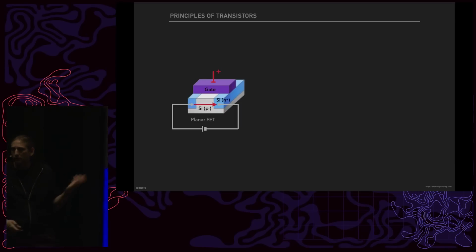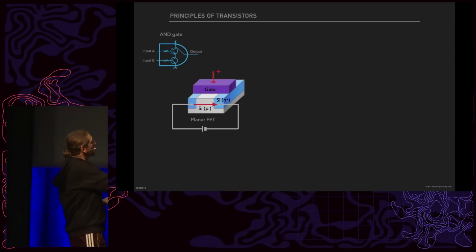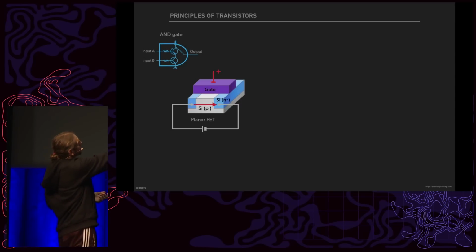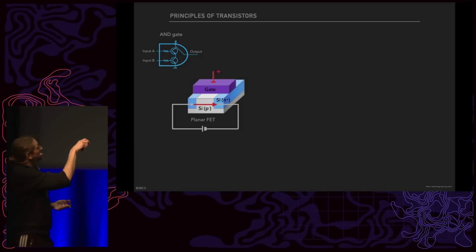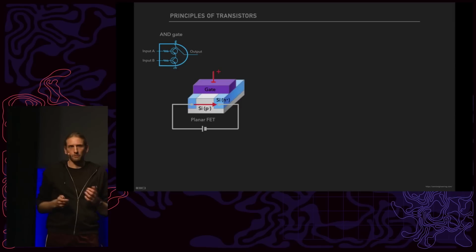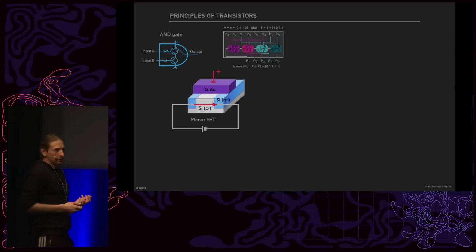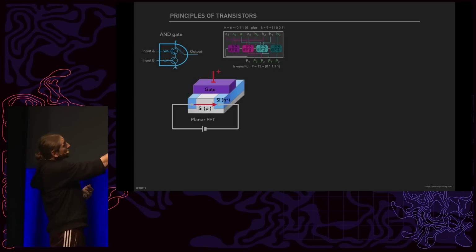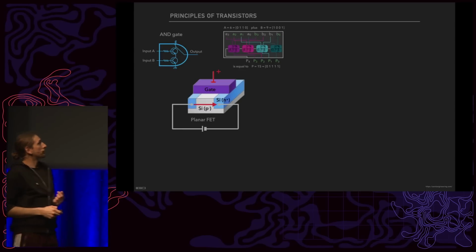And as an engineer, these kinds of switches are really nice because you can build more complex structures, for example this AND gate, by just combining 2 transistors here. And this AND gate gives the true output if both inputs are true, right? I guess most of you have heard about this. These gates are the building blocks of pretty much every electronic device you can think of. For example, this very simple logic chip, which does nothing else but add 2 4-bit numbers.